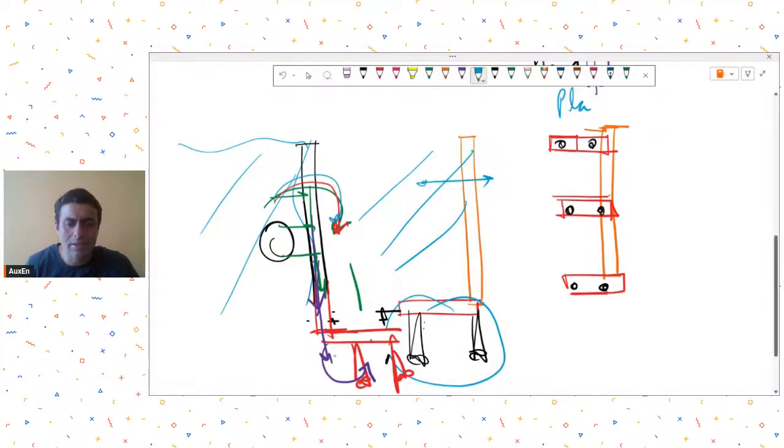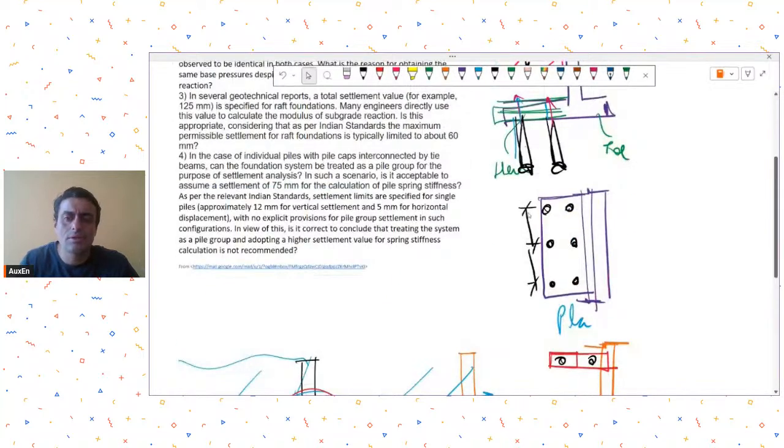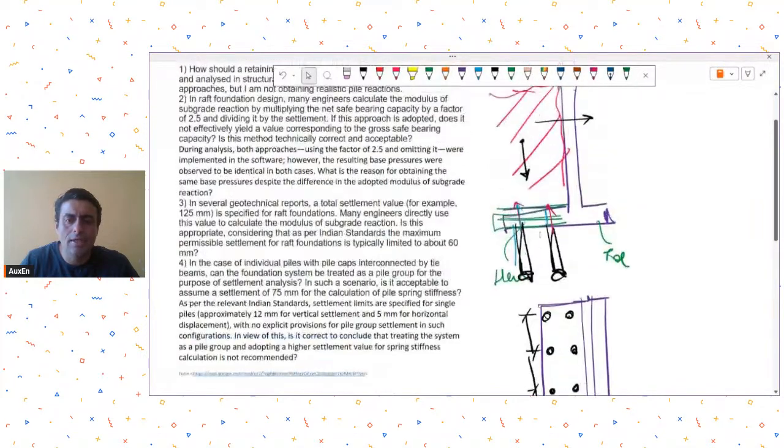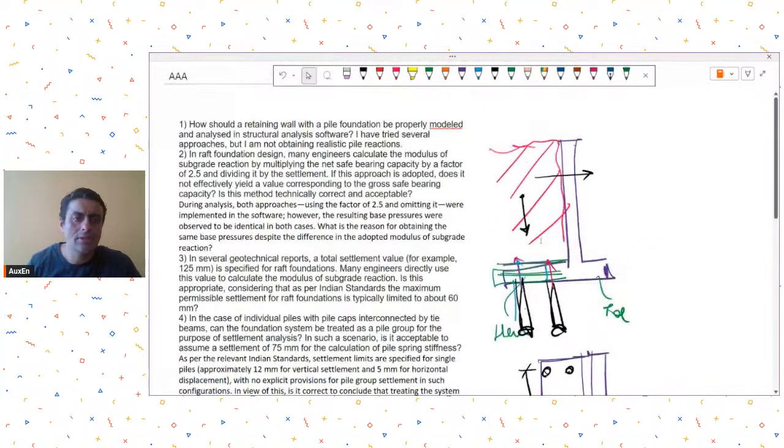And piles you can slightly displace from this face. You can have the pile slightly away, so that the self weight of the wall will create a balancing moment to this overturning moment due to soil. So this arrangement can also be thought of. So whatever arrangement you are coming up with, it will depend on your site conditions and the choice that you are making as a designer.